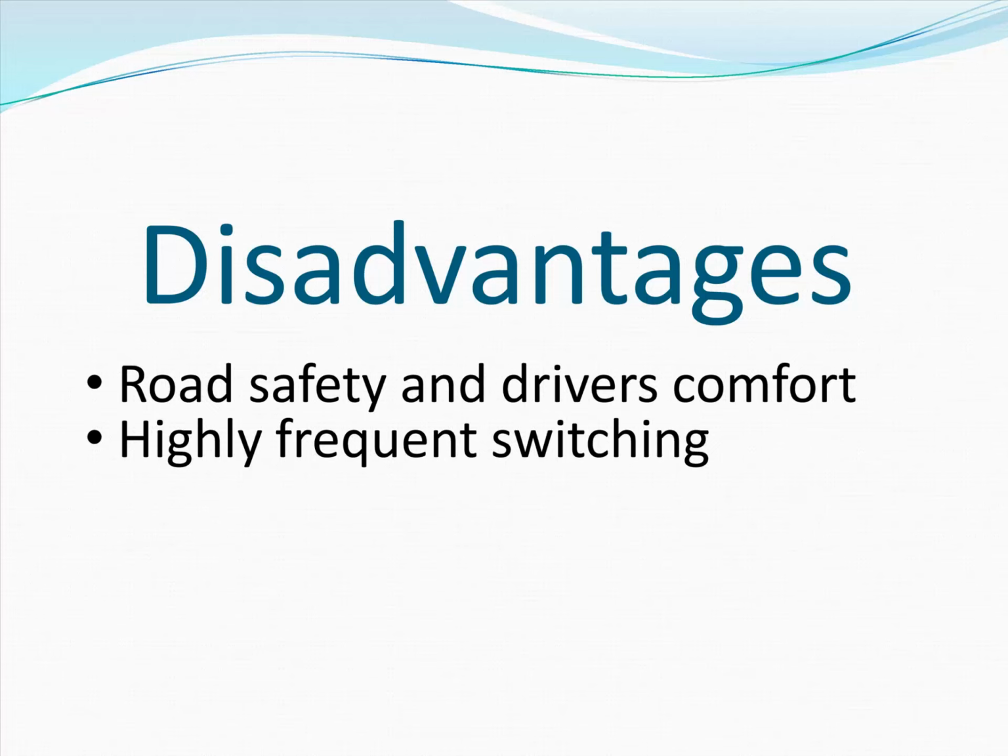So for example, if you dim light by 50% instead of turning it off, you will have half the rate of energy saving. So in our case, the 57.4% saving when you turn lights off will be reduced to only 28.7%.